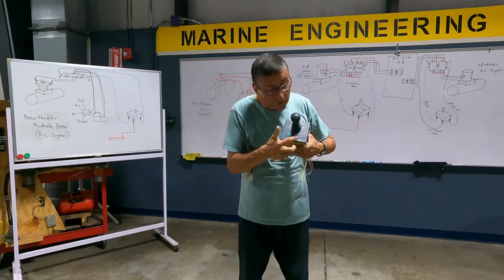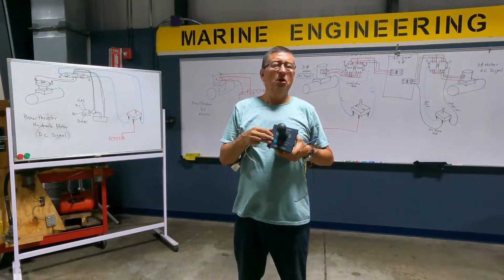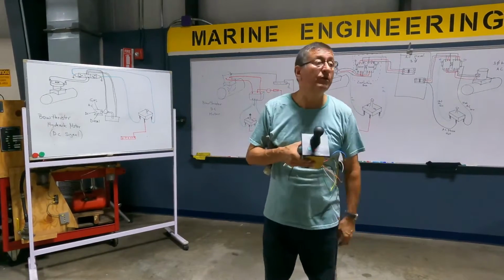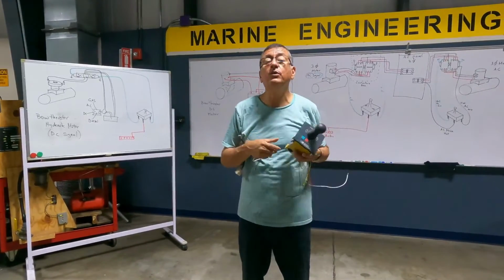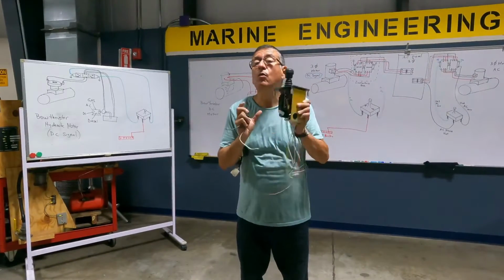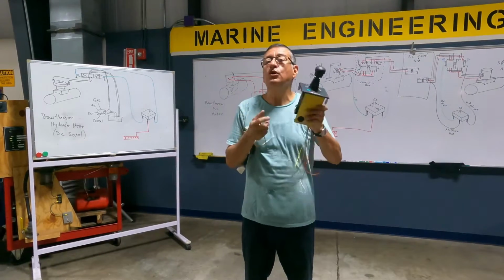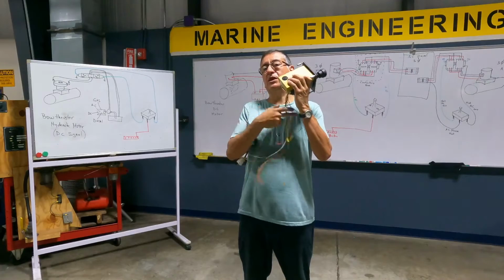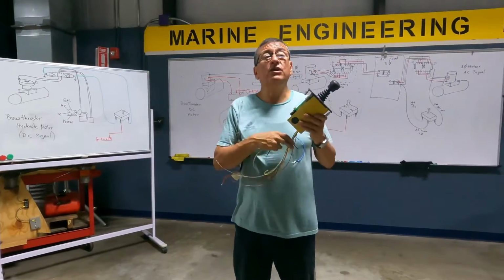This is the power for the lights, right, and the computer that I have here. How do I know that? Because you study electricity, advanced electricity and electronics. With what electrical or electronic tool do you determine which one is which cable? The DVOM, the voltmeter, with the voltmeter and the continuity test.